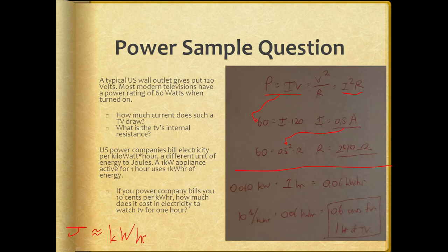It's the energy that a 1 kilowatt appliance, an appliance with a wattage of 1,000 watts, uses if it's turned on and used for a total of 1 hour. So 1 kilowatt hour is literally a 1 kilowatt appliance times a 1 hour runtime. So in general, to find the kilowatt hours used by a machine, you want to take its wattage, convert it to kilowatts, and multiply it by the amount of hours that it's active.